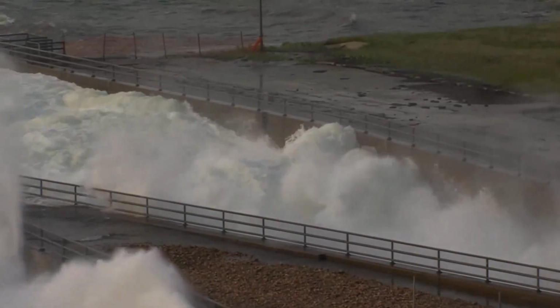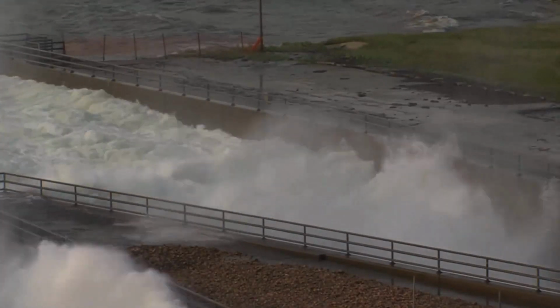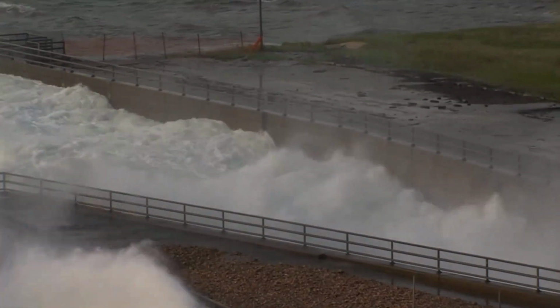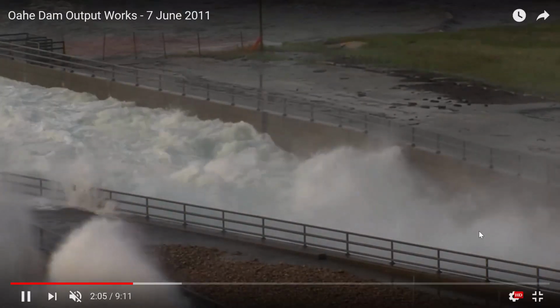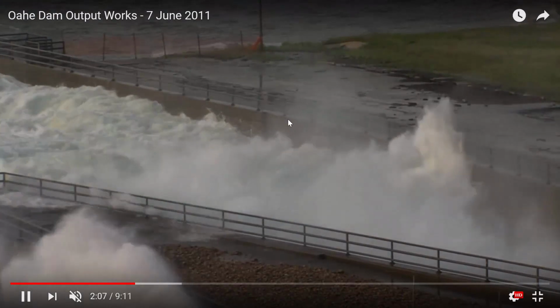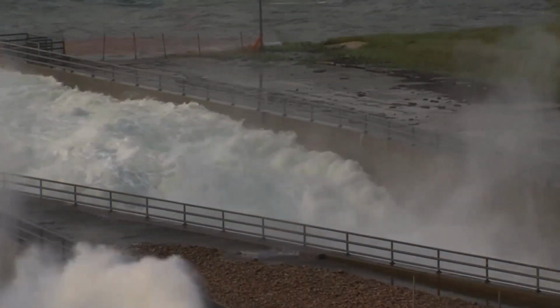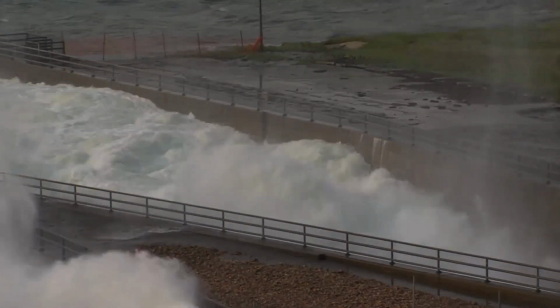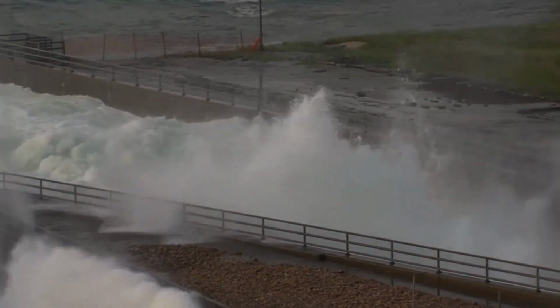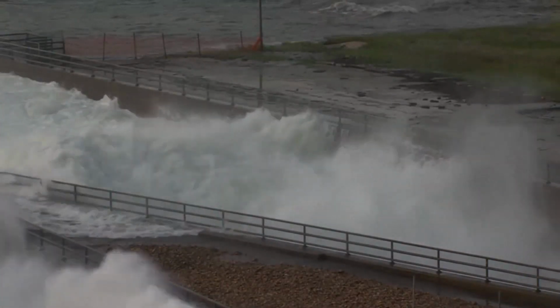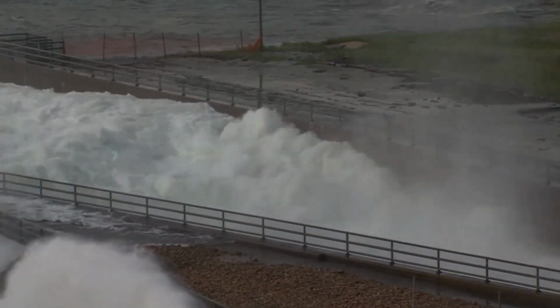So not only is it bad from an environmental standpoint, but it can threaten the safety of the structure itself. Like if you have a discharge of high velocity water just straight from the dam with no sort of stilling basin and no sort of concrete armoring like we see here. So if you just had that immediate release in the close vicinity of the dam, then that scour could gradually cause the erosion right up to the surface of the dam. And then you have the threat of a structural failure of a really important piece of infrastructure.